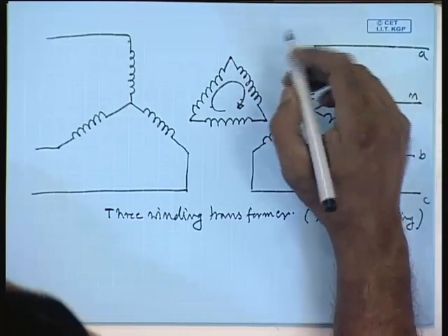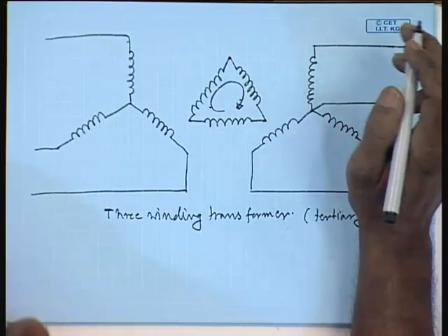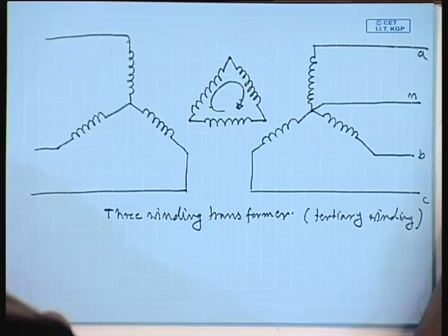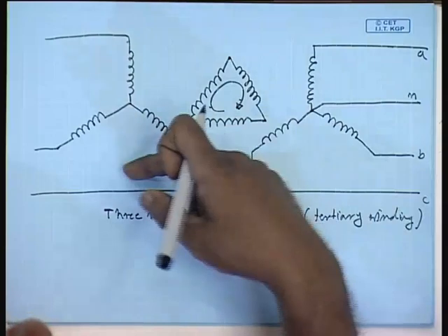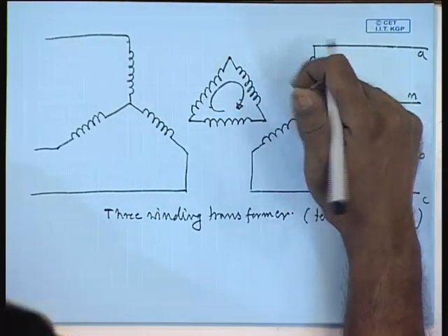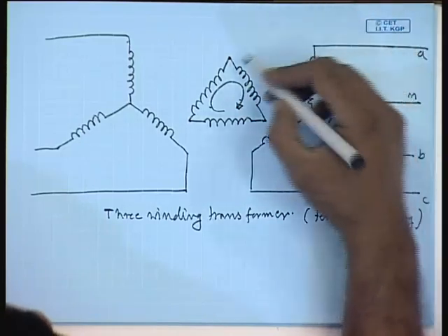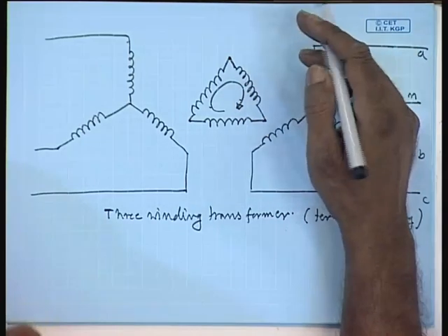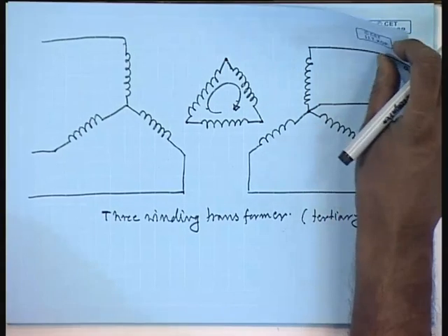For example, if this is used in a substation, this third winding can be used to supply auxiliary power, which is at a very different voltage than the conversion ratio of this transformer, or this can be used to connect a capacitor bank for supplying leading var to the bus. Now, in this lecture we will see how to analyze this 3 winding transformer.